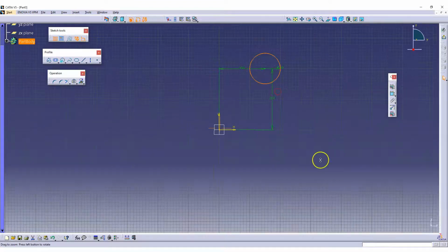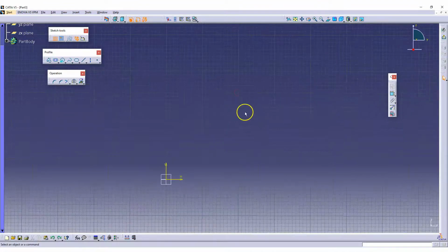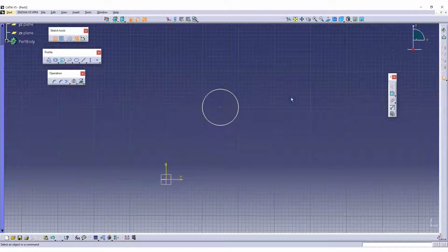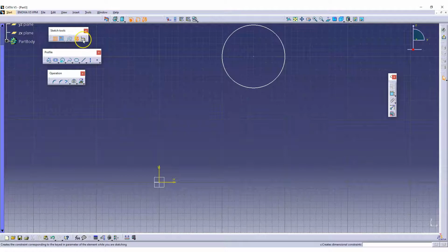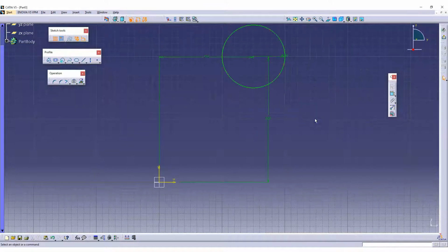Give it, what happens? You get a circle default with fully constrained, right? The moment you make it off, this one, right, and use the same sketch and give the same value, see that it is not appearing. That means you need to give the constraints once again. So always ensure this should be on. The moment this is on, and now you just create the same coordinate circle with the same value, you can see that the sketch is fully constrained.